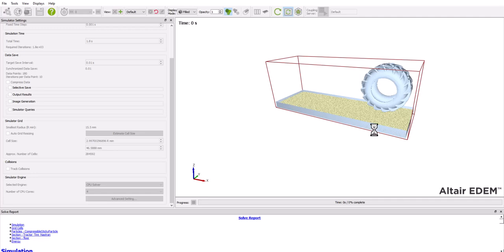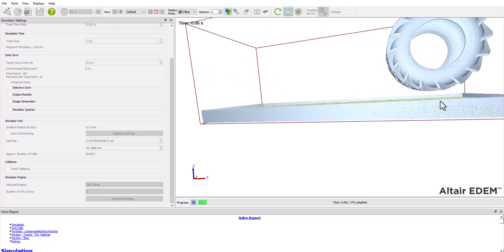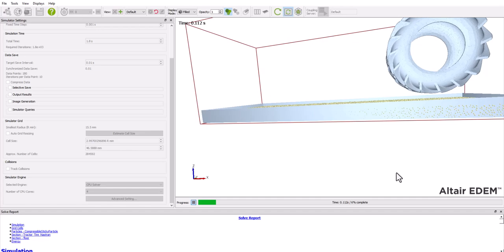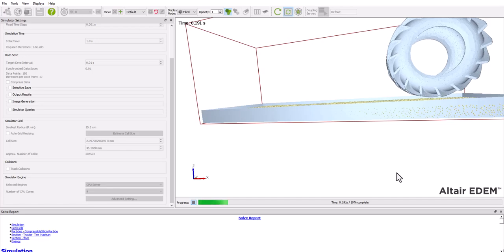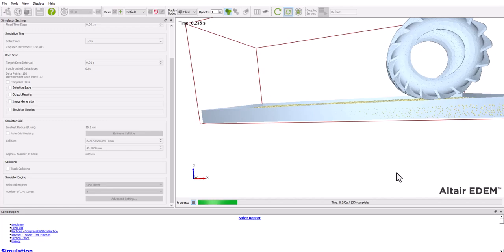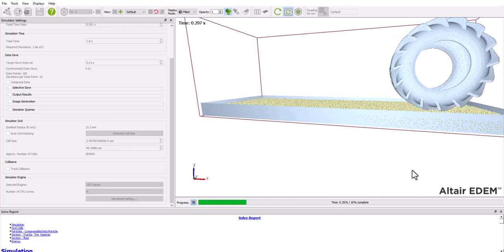And if I run this rigid tire, what I should expect to see here is the tire drop vertically, engage with the particles, and have no other motions. This is the way that I normally approach setting up the motions of the tire. I add the first motion, run the simulation because it runs relatively quickly, verify the response. So long as it looks reasonable, I proceed on to the next motion definition. So there's some bounce, that all looks appropriate.